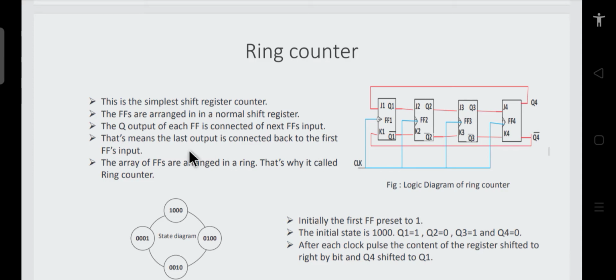In a ring counter, if you want to design one, the arrangement is very simple. We don't have to do much; we just connect the flip-flops as we connect them for a shift register. Whatever flip-flops are given, we connect them back to back, as in a shift register.